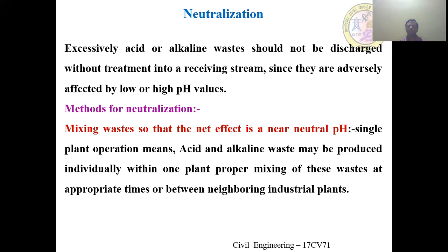The wastes are mixed so that the net effect is nearer to neutral pH. As I mentioned earlier, if some plant is going to discharge effluent of a higher acidic nature, it is going to be mixed with the effluent of another industry which has a higher alkaline nature.